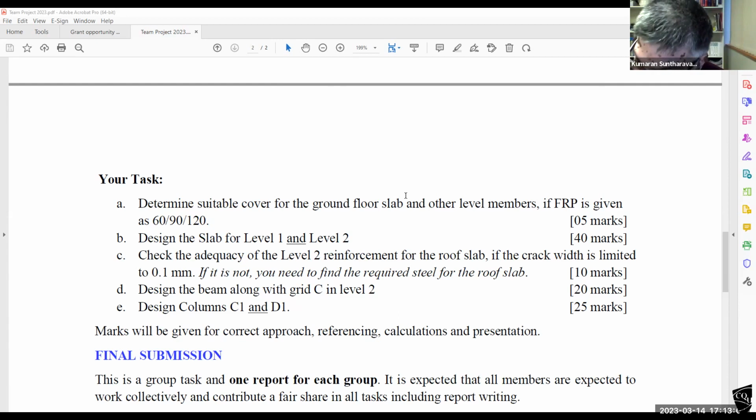So you have the dead loads. And when you get those numbers, if you get the number from Appendix A of AS 1170 part 0, you should write that reference from Appendix A, AS 1170 part 0. You should put those details in the submission. Otherwise, if you just put the numbers, it's not good enough. Okay. So find out dead loads.